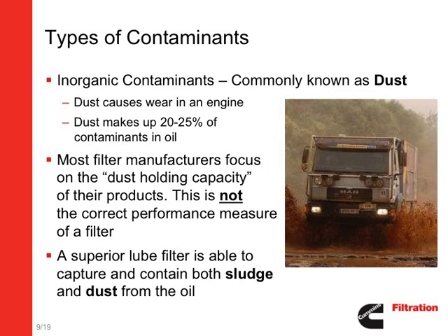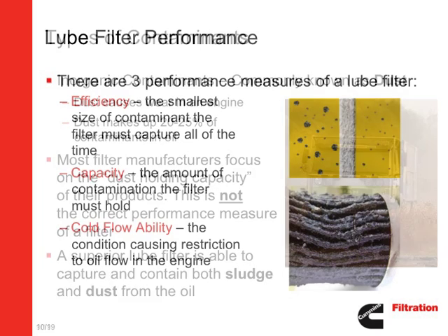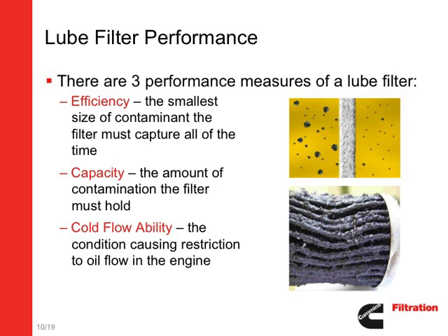The inorganic contaminants, commonly known as dust, cause wear in an engine and make up 20 to 25% of the total contaminants found in engine oil. Most filter manufacturers focus on the dust holding capacity of their products. This measure does not correctly represent the performance of a filter. A superior lube filter is able to capture and contain both sludge and dust from the oil. Just removing the dust and leaving the sludge is tantamount to leaving 75% of the contaminants in the oil. Unacceptable.